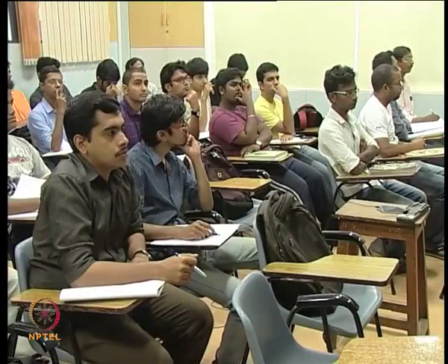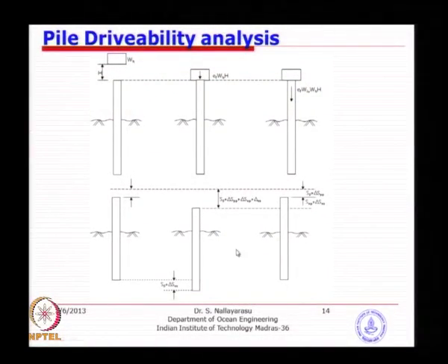And when it is impacting onto the pile, it transfers the weight as the impact energy and transmits to the pile material, having elastic, elastoplastic compression if it is so high, and then plastic deformation for sure.